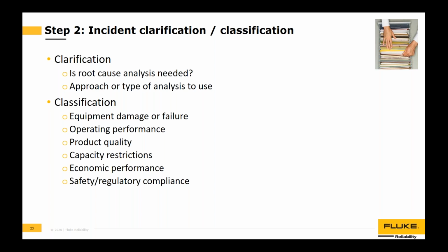The question is, when you are preparing an RCA, who do you include on the team? Well, I would first want anyone operational, maintenance, electrical, whatever, that was involved in it, because they're the eyes and the ears as to what happened. Probably also a subject matter expert, someone who knows that system best. In some cases, that is a system engineer. Sometimes it's a reliability engineer. Sometimes it's the OEM, depending upon what it is.